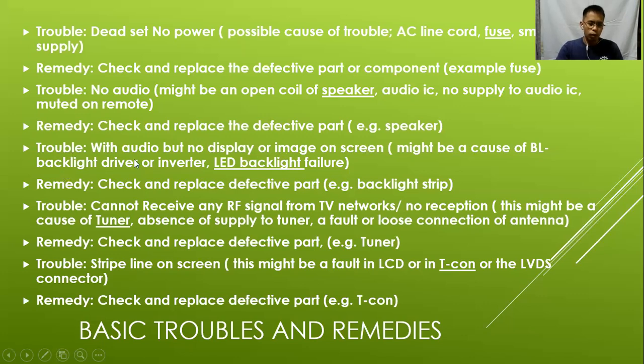Okay, another trouble with audio but no display or image on screen. So the possible cause of this trouble is backlight or the backlight driver or the inverter.